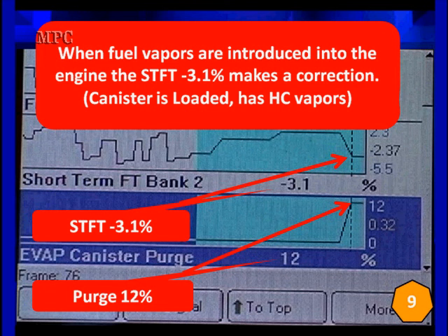Now, the way you use this advanced graphing technique is you look at the same instant EVAP changes, and see what happened to short term. You can't evaluate short term up there to the left when EVAP was off. Now, we don't turn EVAP on until we typically get around 155, 170 degrees Fahrenheit, somewhere in that range.